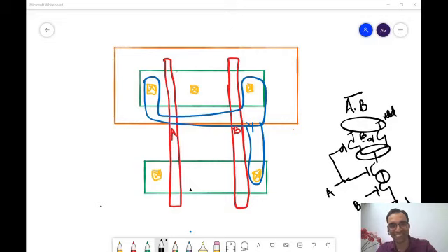Sir, there can be two things. One thing is in the current configuration, you are taking the metal over the poly 2 times. And if you do the VDD on both sides, then you have to take the rail going above for the VDD, but it would not be over the poly. It would be at a minimum DRC from the poly. Maybe you can increase that if you don't want to lose the area, and decrease the capacitance also. Okay.